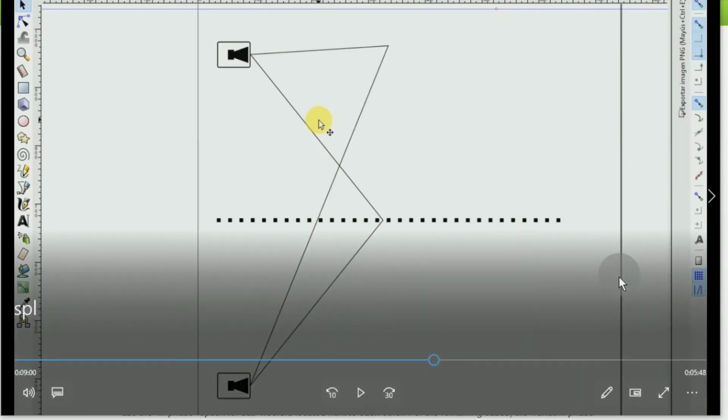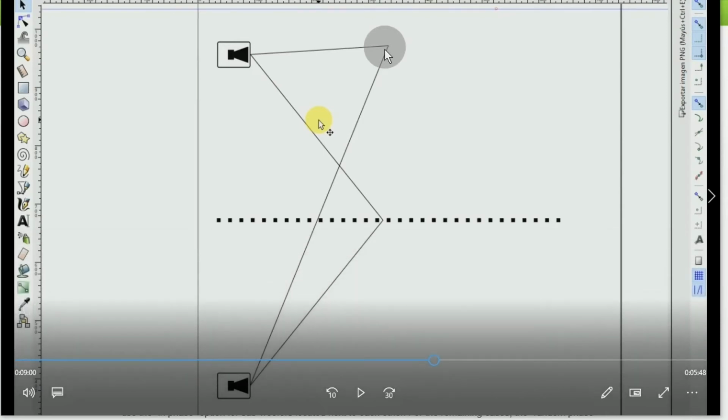However, for any other positions outside of this center line, the time arrivals from the sources would be different, and that would mean the possibility of interference. Depending on the frequency and the time arrival difference, we might get total summation if we're lucky, 6 dB more, total cancellation if we are unlucky, or somewhere in between.